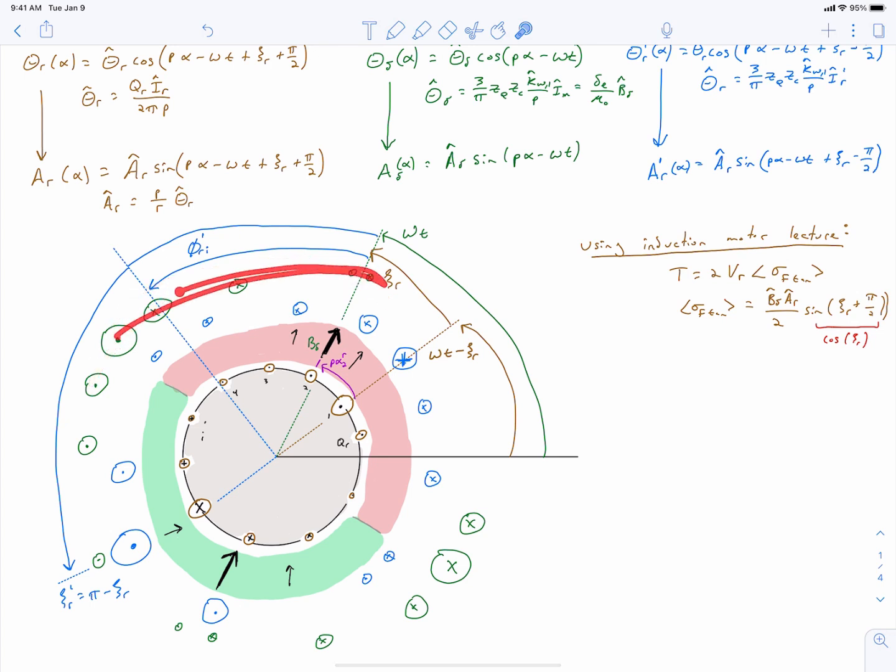This linear current density that we've drawn in green is aligned with our magnets in a way that it can create no torque, and we proved that in our AC machine design sizing video. So therefore, we can see that the only current density that is capable of producing torque on our stator is the blue current density, whereas the green current density is just required to establish the magnetizing field.